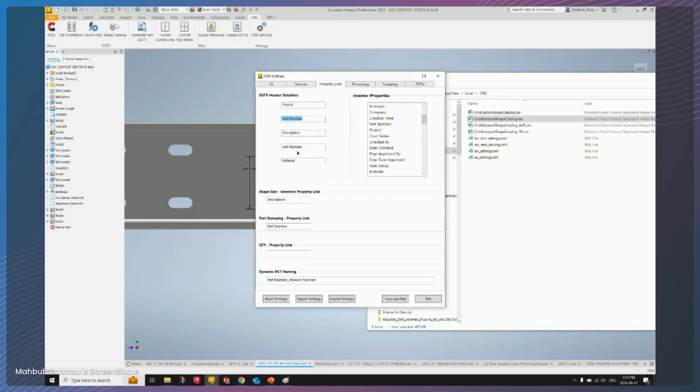The reason why we kept it on the part number is that some of the software, on the CNC softwares, right? The software that you use with your machine, they will be picking that line 4 as your marking content, your mark number or whatever, and they prefer to have it as a part number, right? So I put it on line 4 as well. And as I said, those are depending on your needs and depending on your machine, right? And the line 5 is the material grade normally, right? If your machine really needs that info, you can go ahead and include that one, right?